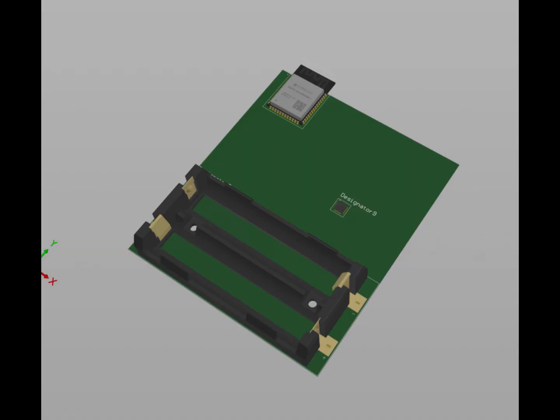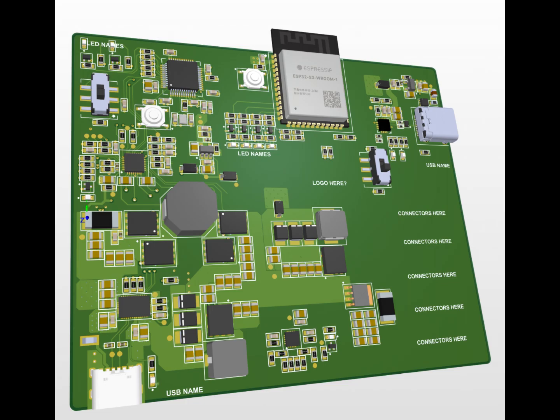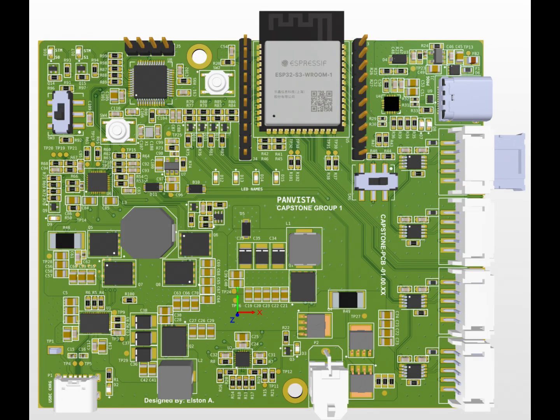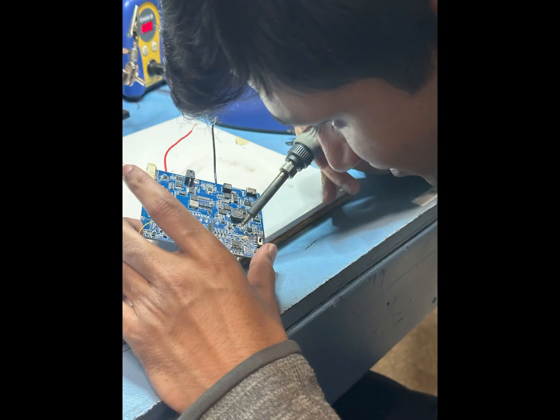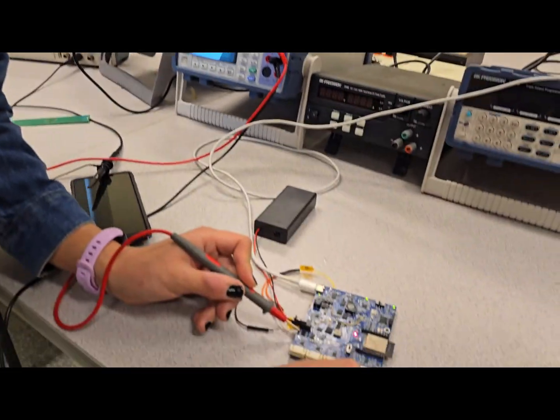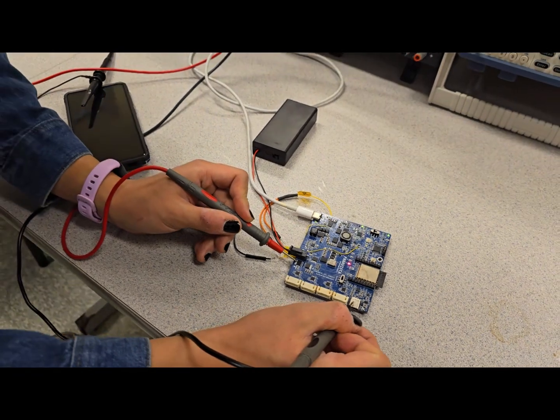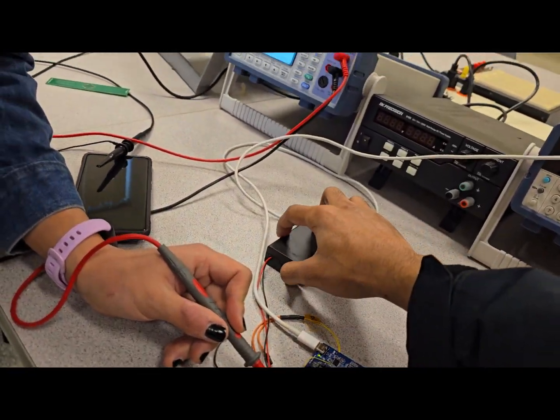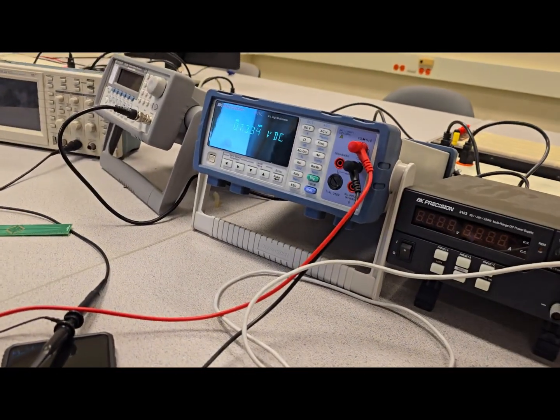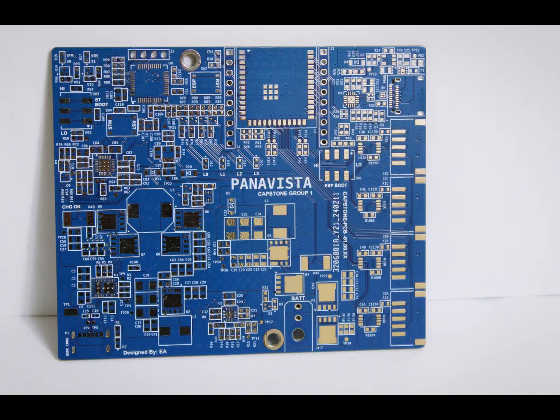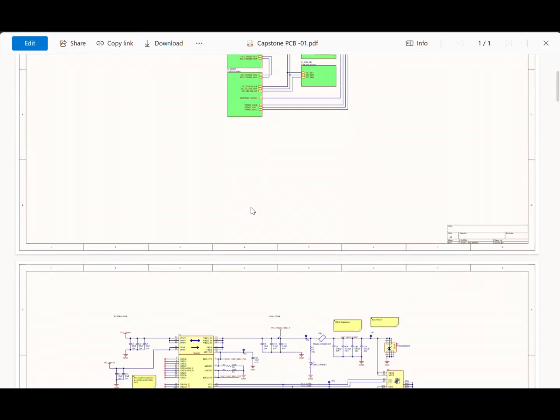In my module, I was working on the headset, a way to integrate the IMUs and also enable wireless communication between the headset and the base station. The idea of building a PCB was assigned to me. We enabled connecting up to a LiPo battery or lithium-ion battery, also providing battery charging. Additionally, peripheral devices, or anything that wants to be powered over USB-C. All of this would be on one board, connected down to the base station, where it would send all the IMU data, creating the schematic, and then doing the layout.